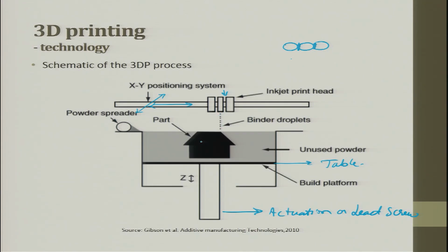After this, the part can be immersed inside another polymer, varnish or something like that, so that the outer core layer is stiffened. So here the part need not have very high strength. It is only to give a form, shape by this process. After this, you can use this as a pattern for making a mold to a component, etc.